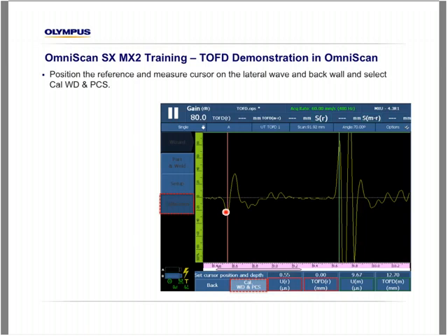There is a measurement taken at the peak of the negative wave. Also, in some cases, that measurement might be taken here, directly between the negative and positive. It's important to be consistent and use your training and work practice. The overwhelming majority of the measurements are taken directly from the first negative peak. And again, the OmniScans always break negative first because they have a negative square wave pulsar.